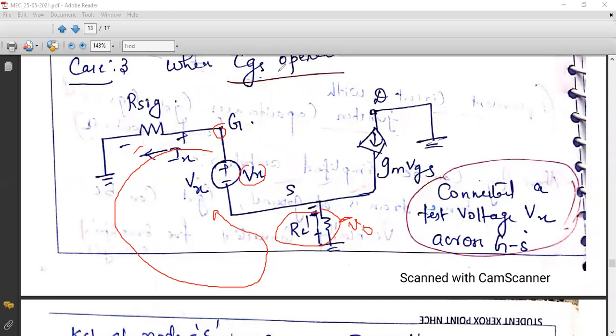So based on that concept, I can write my equation as follows. I hope you understood. Already you have studied these things in third semester, how to apply KVL. You go through the direction of Ix, then see the polarity, and accordingly put negative and positive symbols. If you are moving from positive to negative polarity, you put a negative sign. If you are moving from negative to positive, you put a positive symbol.